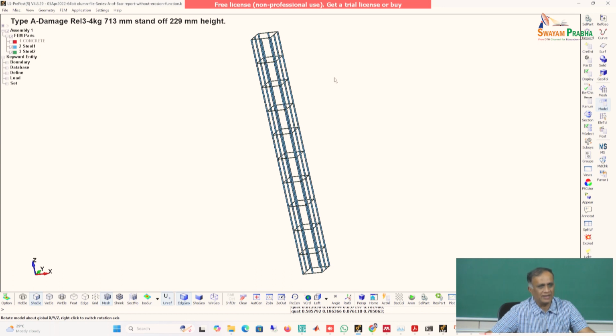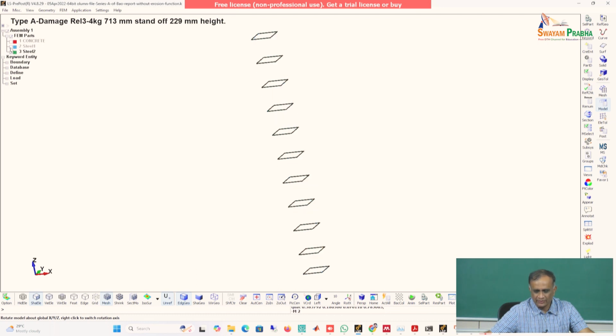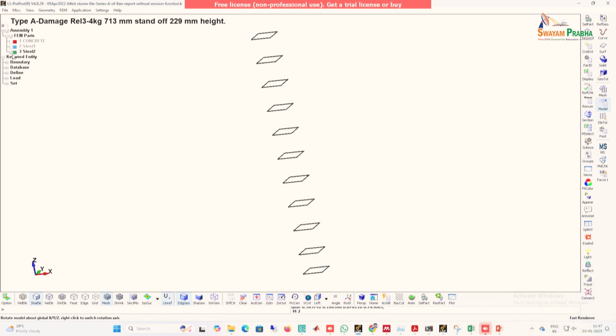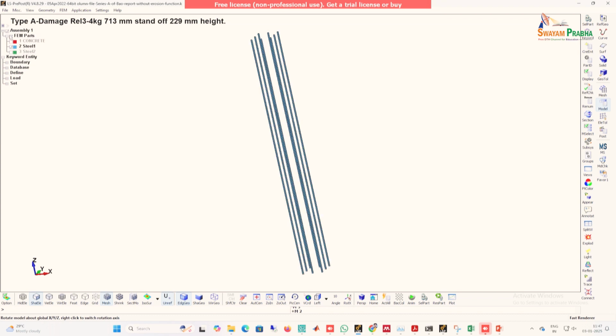Here you're using actual finite elements. So you have to simulate each of these. I've used beam for some reason, but these are all axially loaded elements, and you have to simulate each one of them. And so it starts with your meshing. Then if you take out the steel 1, steel 2, you have to create all these. So those complexities are there.